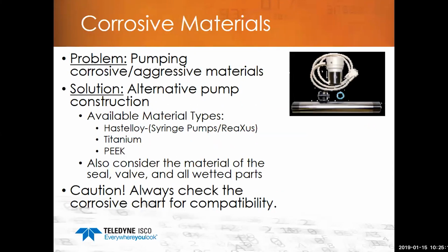Please, please, please, when you've got corrosive materials, make sure you check the corrosion chart for compatibility of the material you're going to be pumping through. The last thing you want to do is find out after you set the application up that, oh darn, this doesn't work with this material, or it's too corrosive for it.